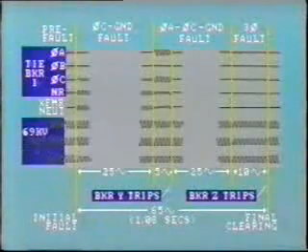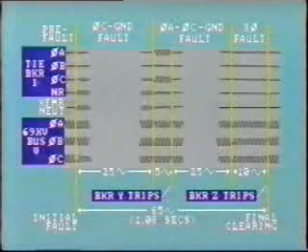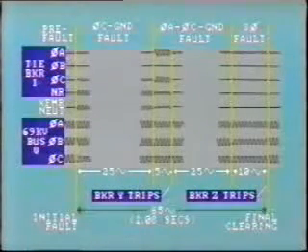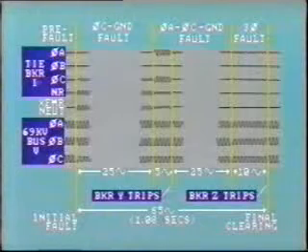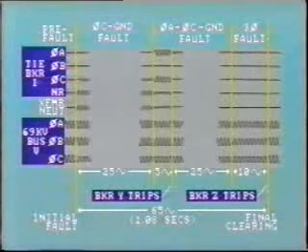The oscillograph has recorded 69 kV bus voltages in all three phases: neutral current in a grounding transformer and current in the bus tie breaker, all three phases as well as the residual current. The total elapsed time between the initial fault and final breaker clearing was 65 cycles, just over 1 second. Notice that we have broken the traces to indicate where the waveforms just repeat themselves.